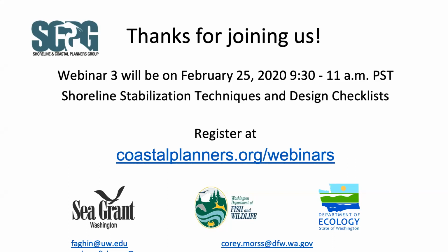Yep, that's for me. So the question is, what about repair? Is the geotechnical assessment required? So generally, the answer to that is going to be no. Repairs generally get viewed by local governments as normal repair and maintenance, and don't require a geotechnical assessment. And probably most likely, again, depending on the scale of the repair, if you're just talking about replacing a couple boards or filling a crack in a concrete wall, that's at a much different scale and a much different level of scrutiny than, say, replacing 50% of a wall or 60% of a wall or replacing an entire wall.